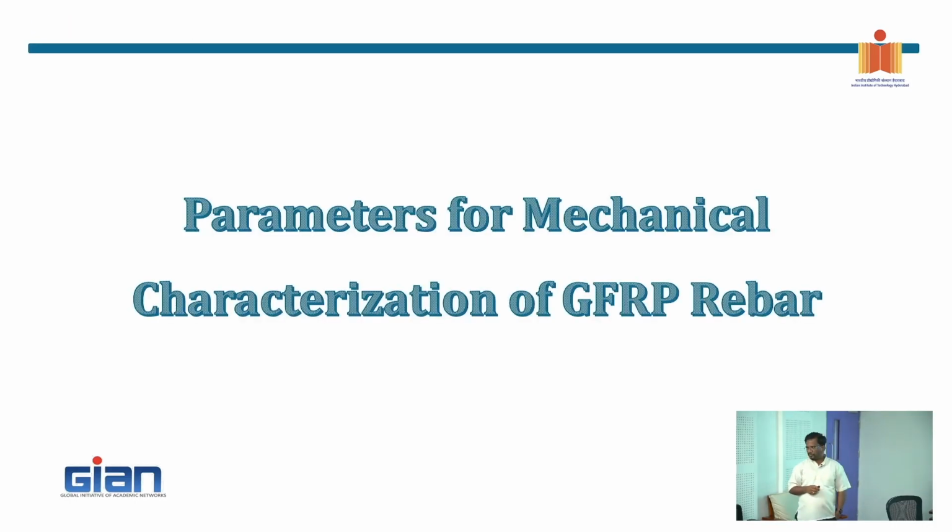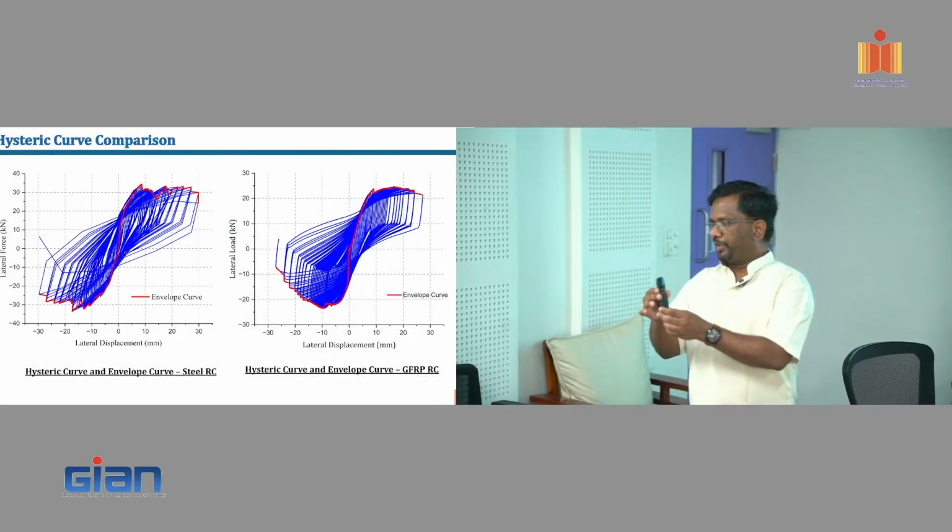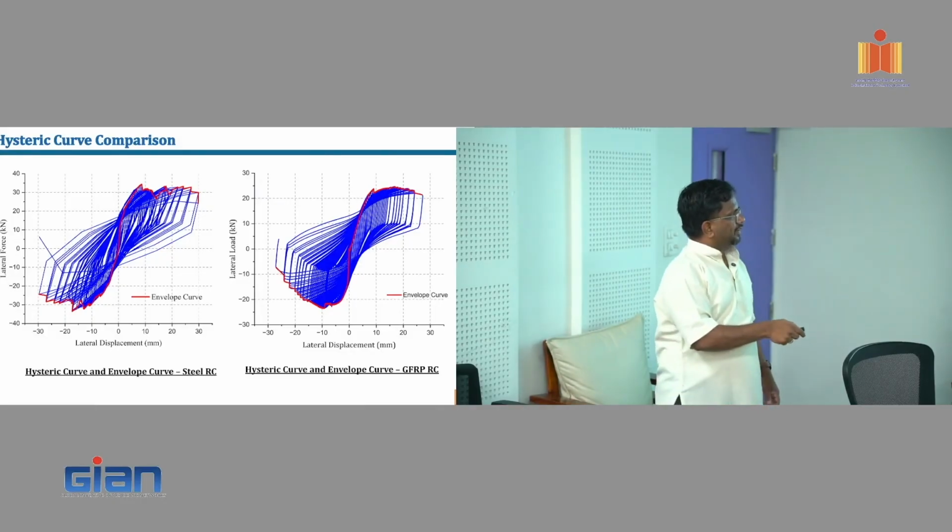What is the residual strain in GFRP as compared to steel? Like once we unload? Well, it again depends upon the level at which you're unloading, right? Within the elastic range, GFRP recovers everything. It is pretty much straight. That's another advantage of the GFRP system. If we keep cycling it, there will not be any residual deformation. It can come back. But once it reaches failure, then it is a different thing, right?